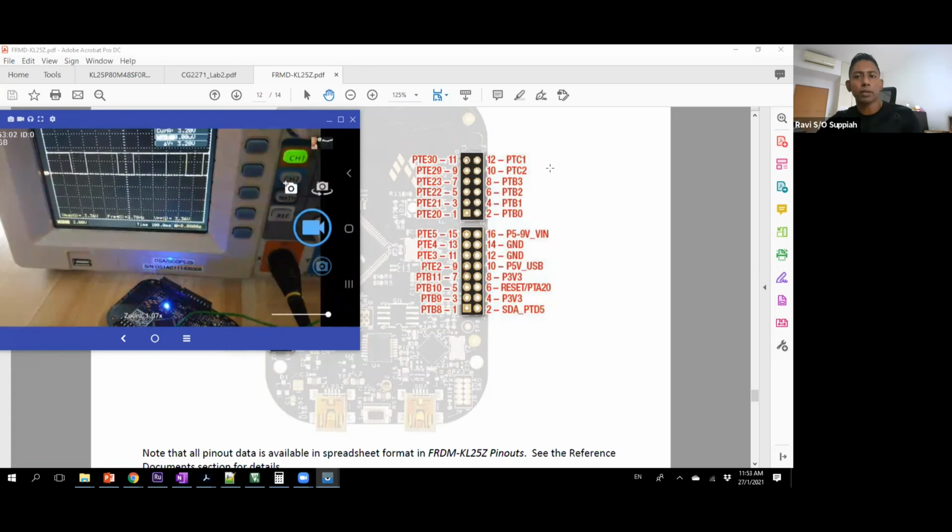This is especially important because in some of the labs, I will have certain requirements where I only want red and green to be on, blue to be off, or something like that. But if your device driver is written such that only one can be on at a time, or when you switch on one, automatically you switch off the other, then you will have difficulty implementing this kind of functionality. So try to create proper library functions to control LEDs individually and also to control them together.